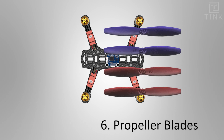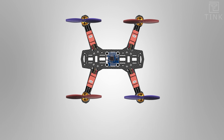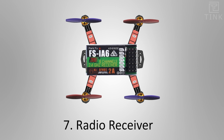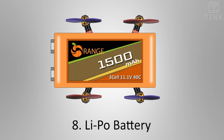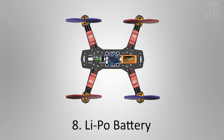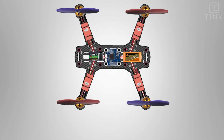To make the drone lift in the air, we would need to fix a propeller blade on each of the 4 motors. To control the drone and get the input commands, we would need a radio receiver. We would also be needing a battery. We will use a lithium polymer battery for this purpose. Lithium polymer batteries have the capability to deliver maximum current in the quickest time possible. That's what we need too. So we can build a drone just using these parts alone.